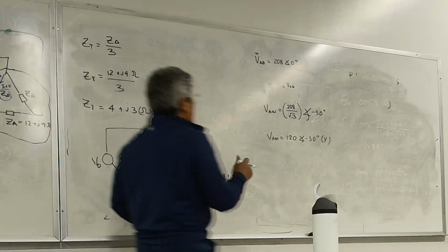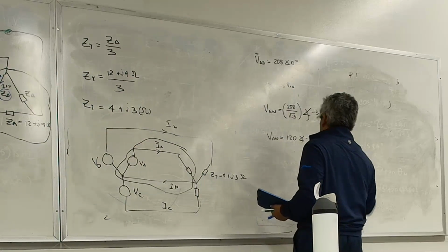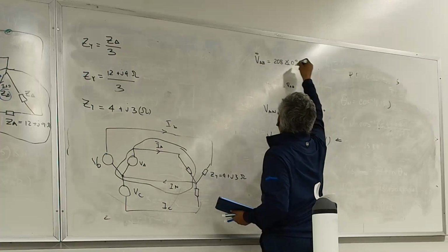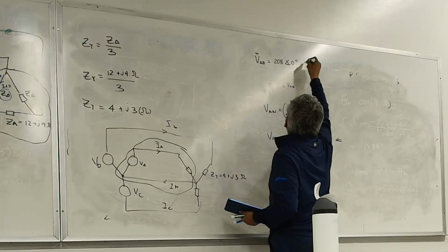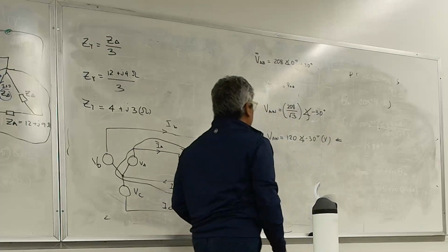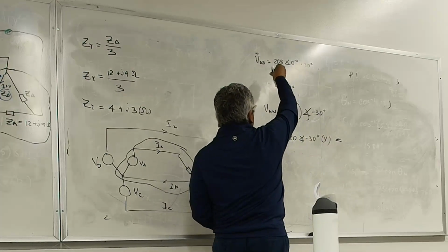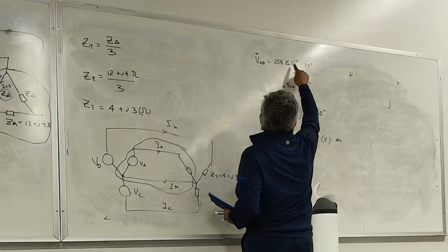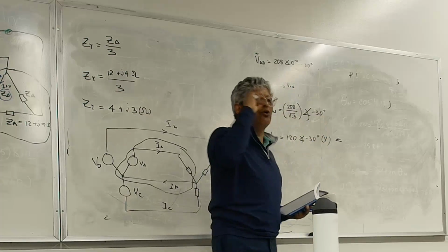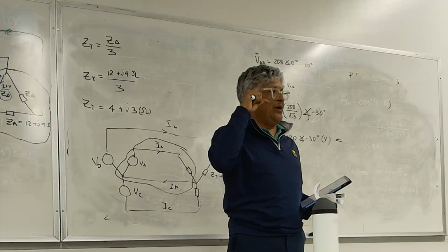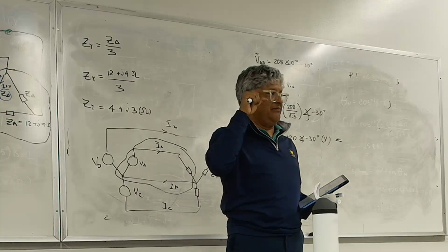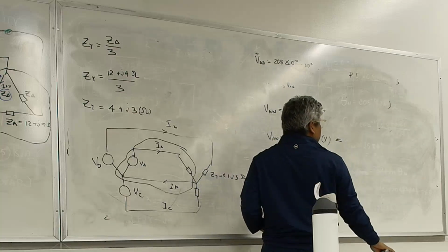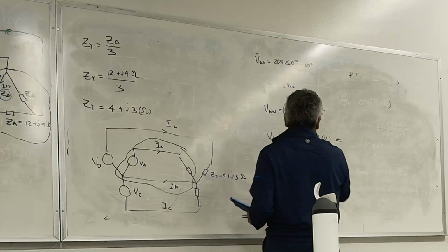Like I said, when we talk about transformers, we'll go back. But the point I'm trying to make is that if I make this AB 0, the angle here is always going to be minus 30 degrees. The line-to-neutral voltage is going to be behind. So if this was 60, minus 30. If this was 10, minus 30 is the angle in between. That's what I'm interested in. Look at my notes and the slides, and follow this problem.